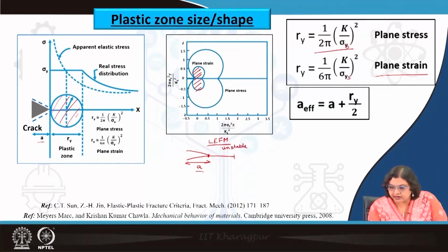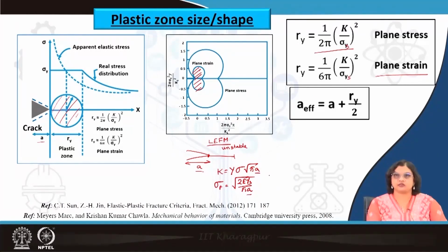and that is considered based on the fact that this entire deformation is elastic or brittle, right. So, that means whatever the crack length is, if we use this in a relation such as K, which is given by Y sigma root over pi a, or even the Griffith criterion, which says sigma f is related to 2 E gamma s by pi a. So, everywhere we consider crack length as the most important term, and based on that we can figure out the changes in the fracture strength or the stress intensity factor, considering that there is no permanent deformation and everything is brittle or elastic.